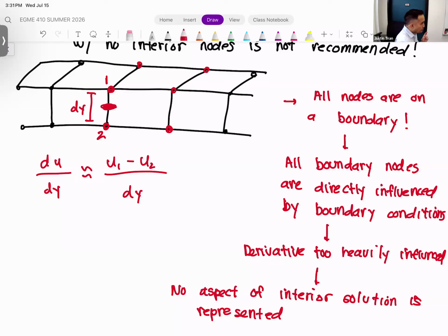So that's why, when you are meshing with solid elements, and this advice is true no matter if you're doing thin geometries or slender geometries, this could even happen for regular geometries too. So this was an issue in activity 2, right? You want to make sure that there are at least 2 elements through the thickness, right? And so if we were to modify this mesh, let's say that we sandwich another layer of elements in here just like that.